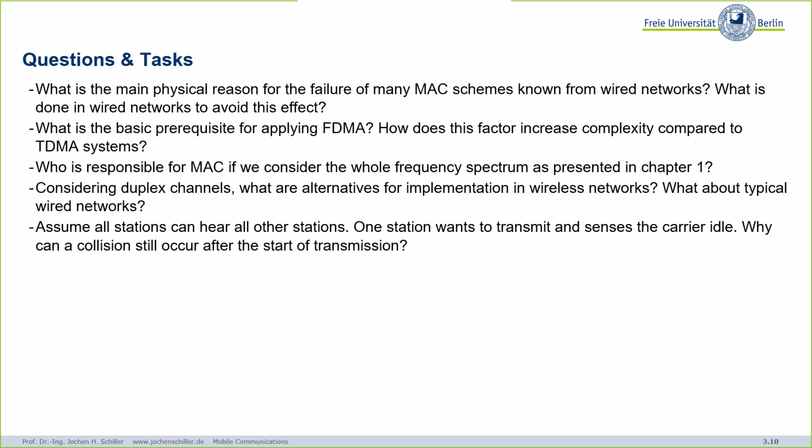In wired networks, duplex. Do you know how this is done in wired networks? Well, DSL is one answer, but a very simple answer. Different wires, right? The phone network you use at home, the classical phone network, has 2 wires. So it's full duplex using 2 wires. But inside the network, the classical network uses 4 wires, 2 in each direction. Well, you need 2 wires for the current to flow. So that's laws of physics. But there you have exactly 2 wires per direction, so you can split this.